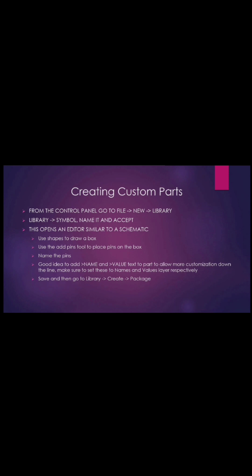and click Accept. It opens an editor similar to our schematic sketch. We can draw, add pins and can name a pin using this setting. Click Save and then go to Library, Create, Package. If these steps are followed properly, a custom part has been created.